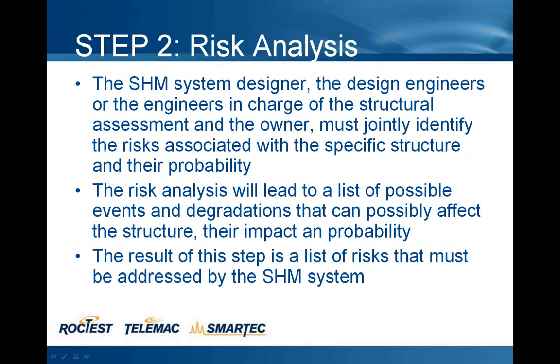Once we have identified the structure that we want to monitor, we can move to step 2, which consists in carrying out a risk analysis. The structural health monitoring system designer, the design engineer or the engineer in charge of structural assessment, and the owner must sit together and jointly identify the risks that are associated with a specific structure and also their probability. So they must say what can happen possibly to that bridge, and is this event a high probability, usually not, a medium probability, a low probability, or a very low probability.